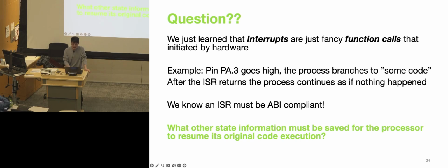A stack pointer. And why is that? Because if the interrupt moves access to anything in a stack, then when the program resumes, the stack is also going to be affected. And actually the stack is where we're going to save all this stuff. So the stack pointer will be increased as we push all those things inside, so yes, the stack pointer will also in a way be stored in this case.